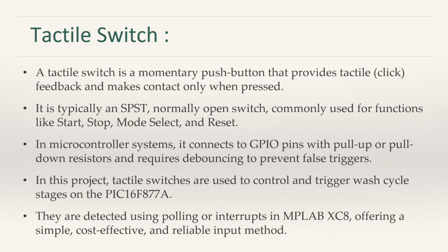In this project, tactile switches are used to control and trigger wash cycle stages on the PIC16F877A. They are detected using polling or interrupts in MPLAB XC8, offering a simple, cost-effective, and reliable input method.